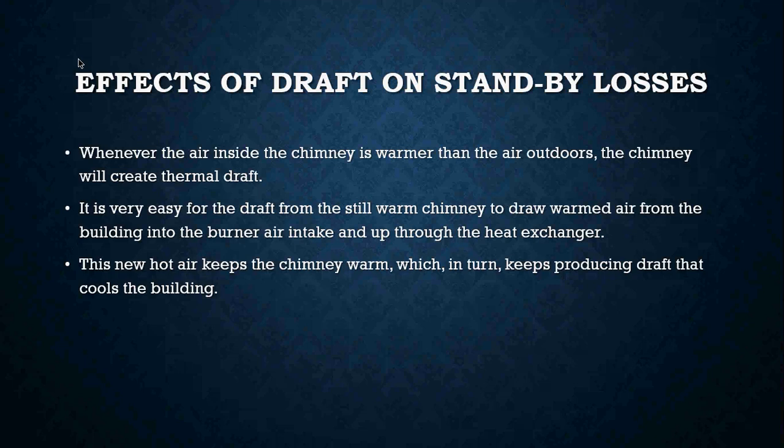Okay, but that's what happens when we have a leaky appliance that has leaks all over the place. Even if that furnace is still sitting there waiting for the next call for heat, it's still warm. The chimney is still warm. I'm still creating a thermal draft. I'm sucking heat and air out of that home.